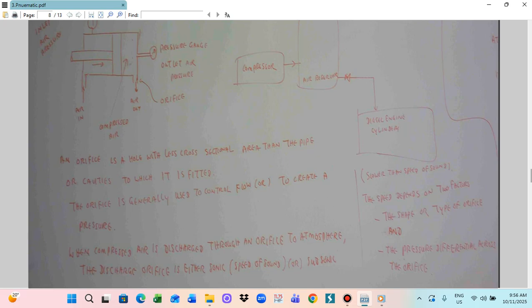Just like that apprentice, this is not from here, this is in Burma, attached to the Burma military aircraft. A new fellow in the Burma Air Force just opened the tire valve without reducing the pressure. As soon as he did, the whole wheel blew out and hit his face. The whole head blew out, and he died instantly. So it can happen like this. The pressure inside the tire is very high, and even a small leak at such pressure can cause injury.